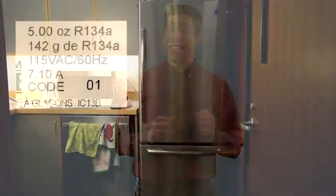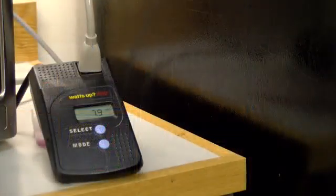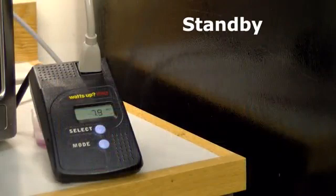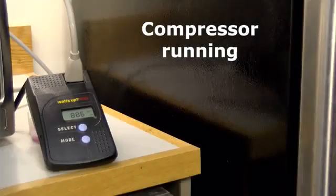Finally, a refrigerator is a bit more tricky because while there's an amperage rating on the refrigerator, it cycles on and off with the compressor, as well as when the light goes on and off with the door open. So it goes very low when the light is off, and then it goes slightly higher when the incandescent light bulb turns on and the door is open, to 94.5 watts. The power then goes much higher to 880 watts at the peak power with the compressor running. So the power consumption is very variable.